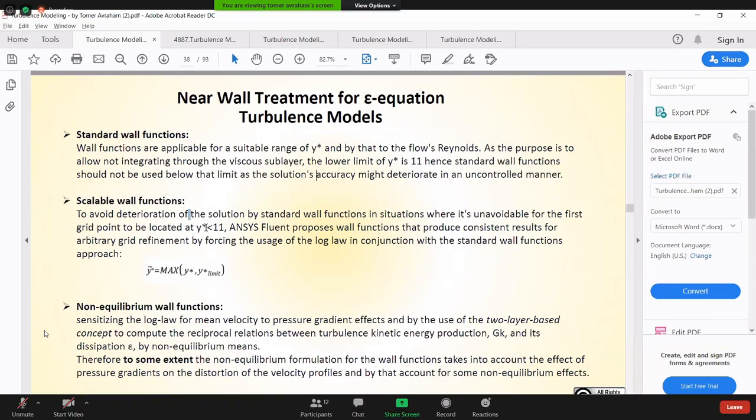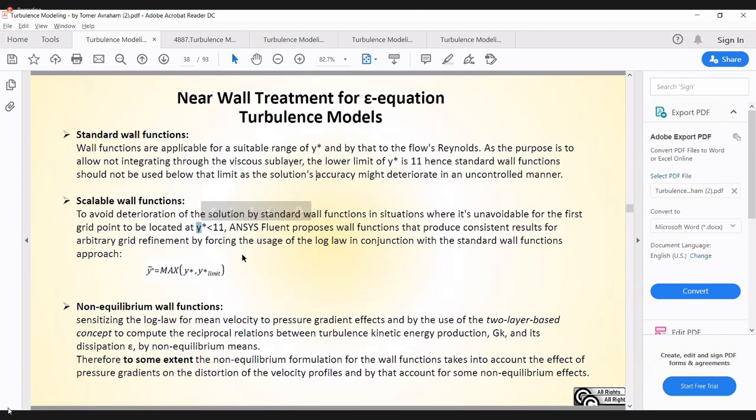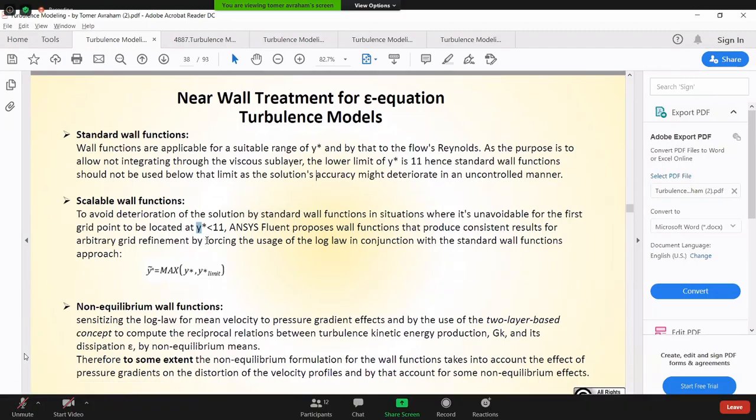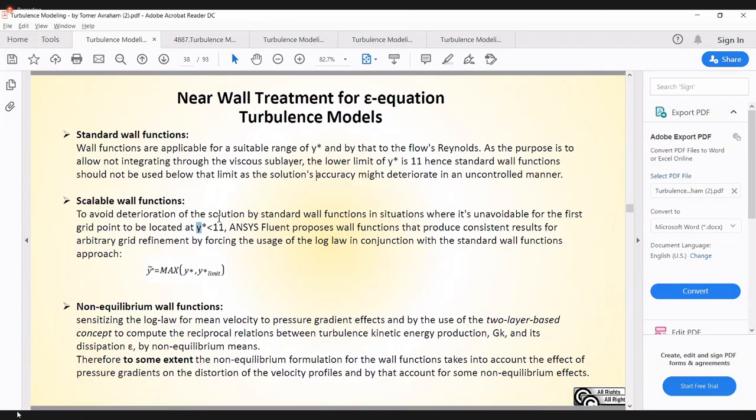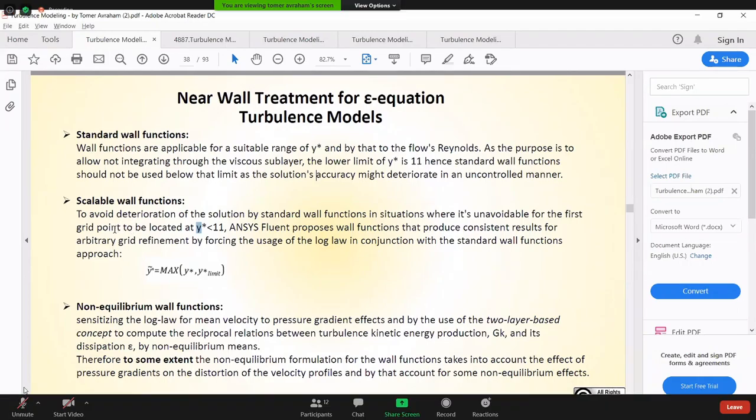I mean, really, I'd rather you do the boundary layer, the orthogonal layers, fine and good enough, and manage the truncation error as much as you can, than listen to someone telling you to use a wall-sensitive model and not check the boundary layer at all.